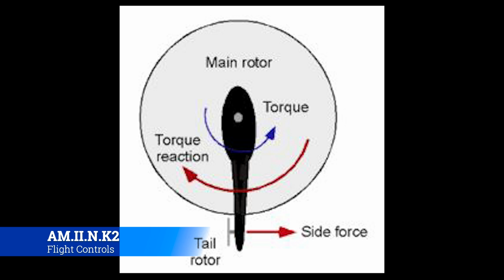Whenever that happens, you have to compensate some way, shape, form, or fashion, because if it doesn't spin at a certain rate, the helicopter can't maintain straight and level flight, or in this case climbing flight. It can't stay in the air. So you have to roll the throttle on to increase the RPMs coming from the engine into the rotor disc to compensate for that, and to keep it right there in that sweet spot, in that little green range of your NP.